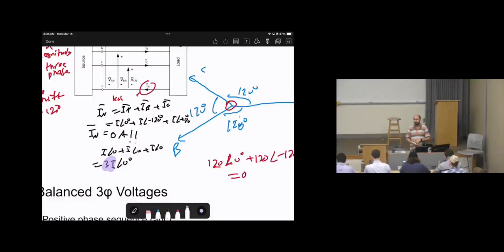And this means the neutral conductor cannot handle it, because 3 times the current will make the neutral heat up, and this will affect the neutral, which is something we don't want, because high neutral current is undesired. Therefore, we choose to have a phase shift so we can get 0 neutral current.